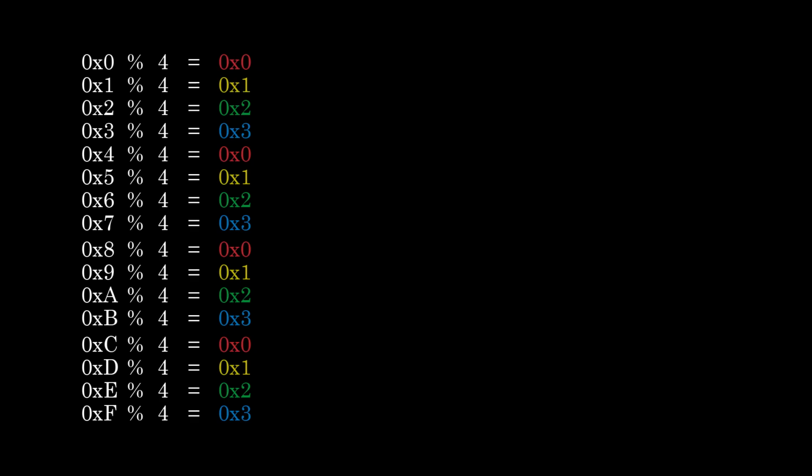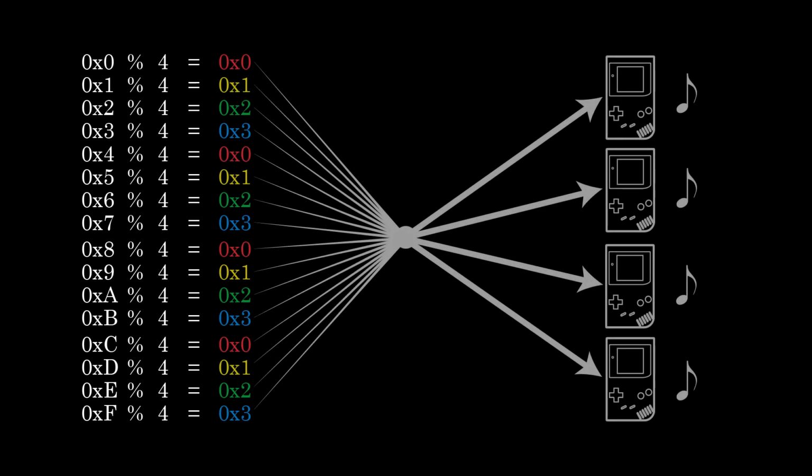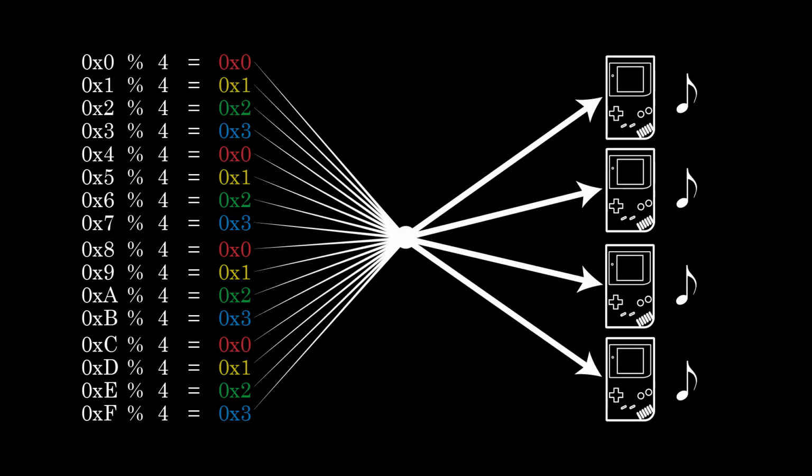If we were to execute such a channel remapping algorithm and then simply send out the converted signals via a multi-plug game link cable that has multiple Game Boys connected to it, all Game Boys of our system would inadvertently always play the same notes. Furthermore, the different MIDI signals of a channel range that has been assigned the same address by the Raspberry Pi Pico would still cut each other off, so this approach would, obviously, grant us no tangible benefit to the Game Boy's MIDI playing capability whatsoever.